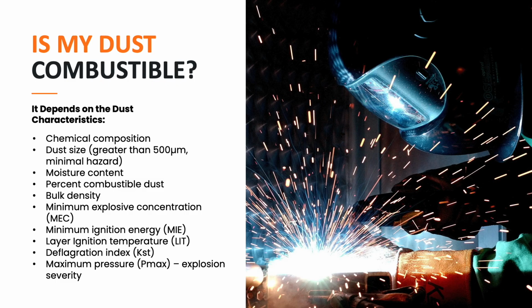And essentially, the first step of that is the lab test, where they'll take about a 3 to 5 pound sack of your dust and run it through some processes to determine its particle size and density, the typical moisture content, and other variables. And they will come up with either a no-go, like it doesn't meet the combustible dust requirement, you're good to go, go ahead and proceed with your business. Or it's a go, it is combustible.